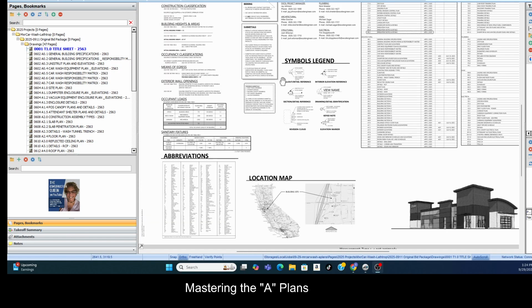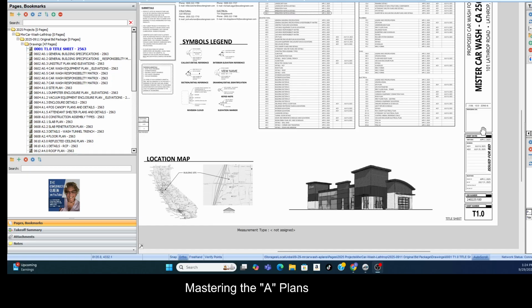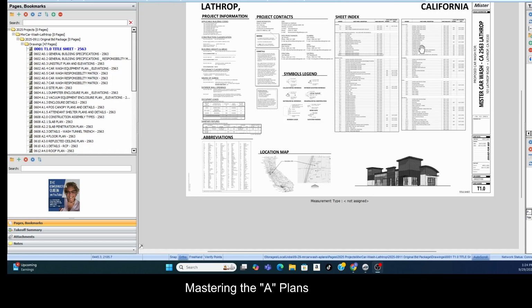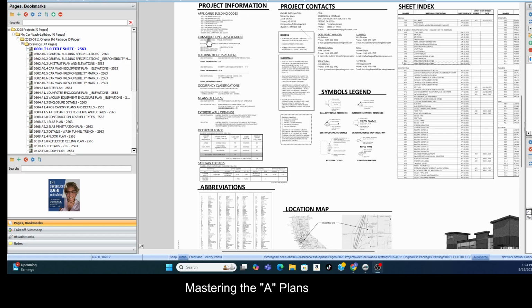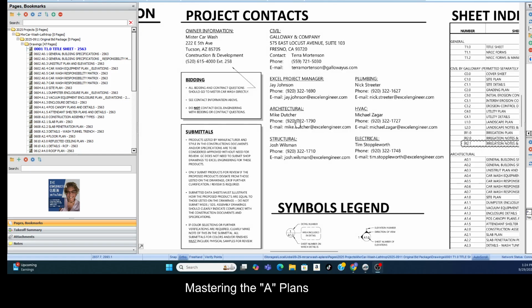So that's good information. Okay, so the cover sheet, very important. Look for that the set has been approved. Make sure of all of that and all the contact information. Legal requirement on the title sheet, cover sheet. Legal requirement that the name of the owner, the architect, and all the engineers be listed.